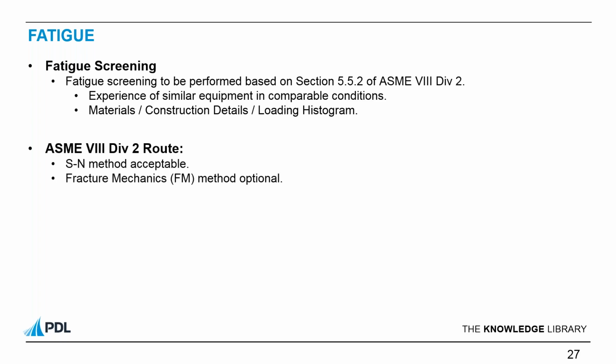If a fatigue assessment is required, the Division 2 route mandates the user to satisfy a stress life approach, an SN type assessment. A fracture mechanics based assessment is optional, however.